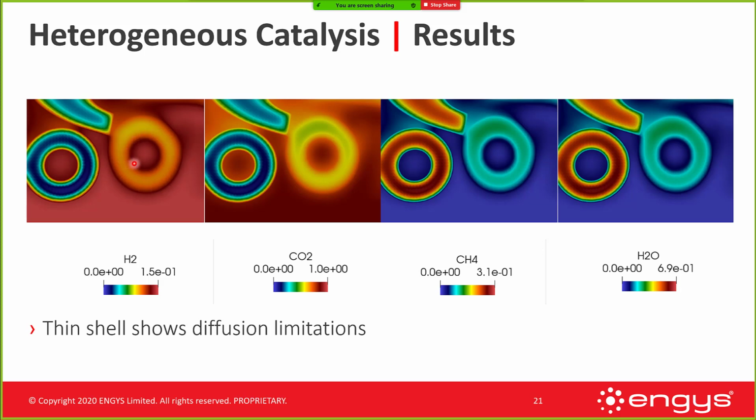And this is interesting because when I ran this case, I specifically selected out this particle and specifically lowered the tortuosity of that particle to see the effect, to see if this was just an anomaly, or to see if this would agree with a phenomenological perspective of, if I removed that diffusion limitation, what would happen. And in reality, what happened was the lowered tortuosity removed these diffusion limitations. So it's actually a very interesting result that agreed more with an intuition that one might have looking at this.